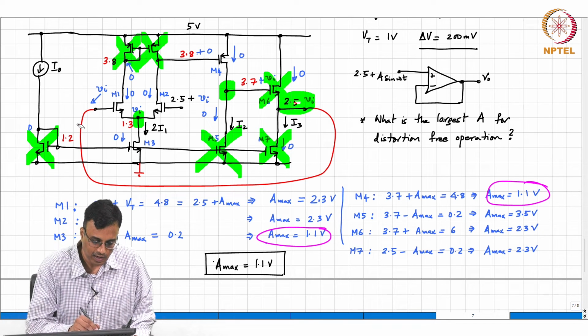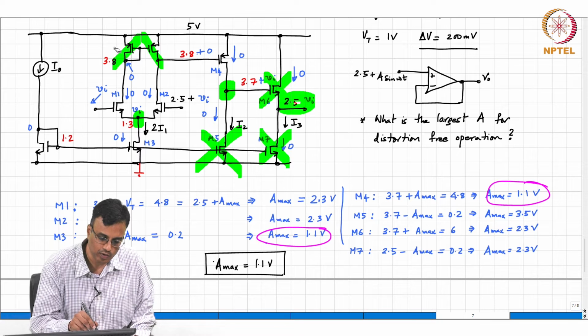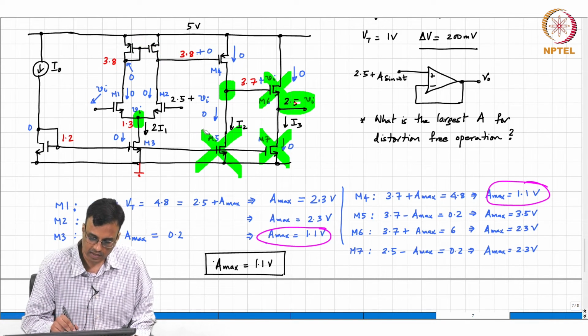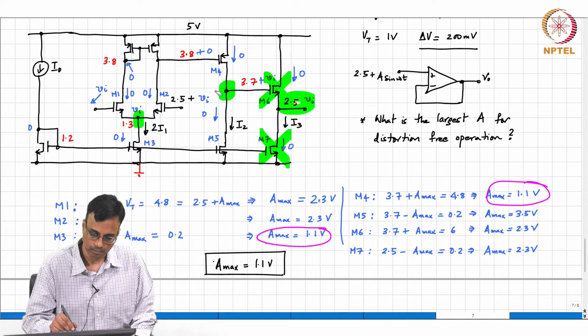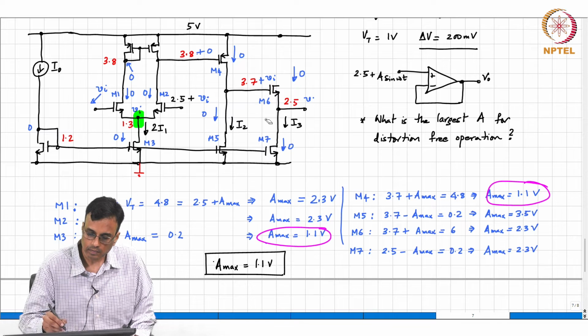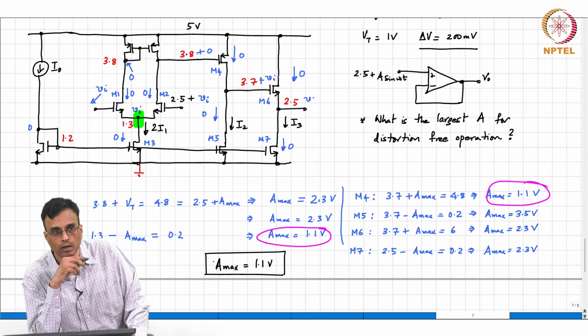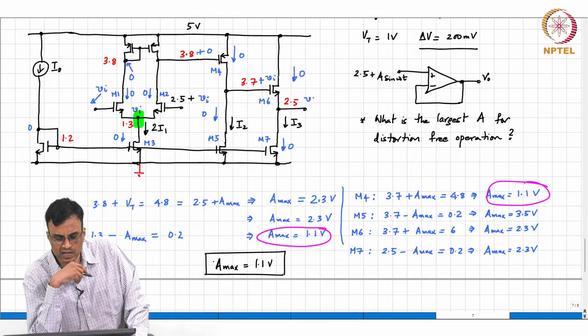In many cases the gain may still not be sufficient. Can you simply tell me a straightforward way of increasing the gain by another factor of GmRo without adding another cascaded stage? No, the M6 is there to give you low output resistance, right? So that doesn't work.